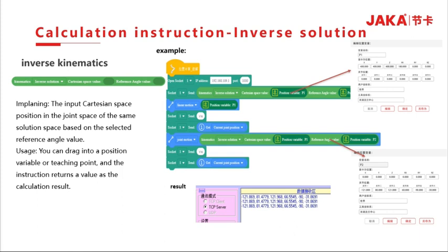After the movement is in place, the socket sends the current joint angle values, and the robot joints move to the result position of the inverse solution. After the movement is in place, the socket sends the angle values of the current 6 joint angles of the robot. The following figures show the result received by the socket, and the result is the same all 3 times.